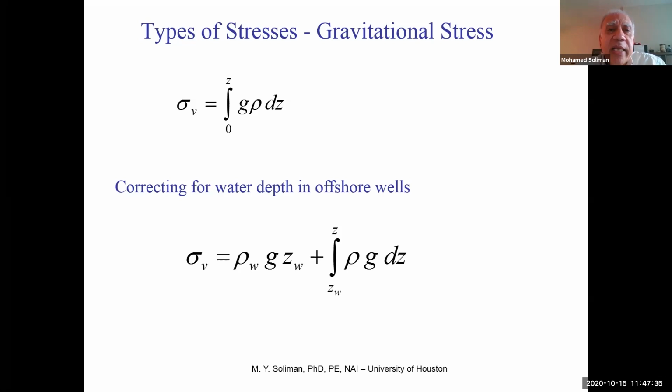If I'm drilling an offshore well and the water depth is, let's say, 2,500 feet, which is not really that deep in what we do now, that will be 2,500 times 0.433. That's a little higher than 1,000 psi, plus the weight of the rock.